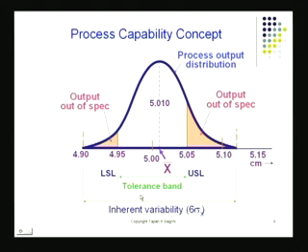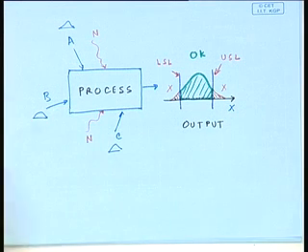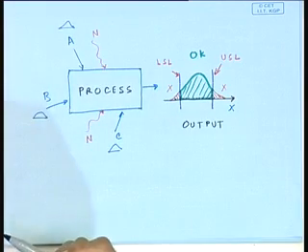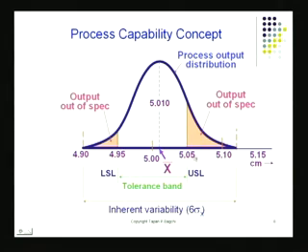Now come back to production. Come back to the process. Remember the process that I showed, when I drew the diagram here. Here's the process. The process is what I'm operating. I as a manufacturer, I'm operating this process. My output may not exactly be fit for the customer to use 100% of the time. Let's take a look at what is happening there. The target has been given as 5.00 and the tolerance band has been given as 4.95 to 5.05. These have come from the customer.